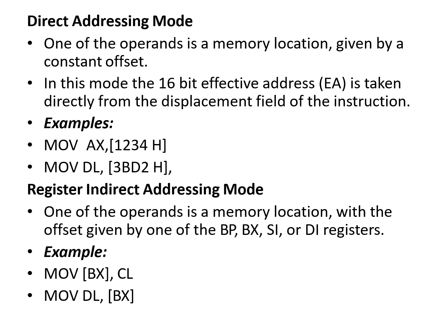By the end of this session, I will explain how the physical address is calculated with an example. Here 1, 2, 3, 4 is the offset, which will be added with the starting address of the segment register. The segment register starting address will be multiplied by 10 or left shifted by 4 times.